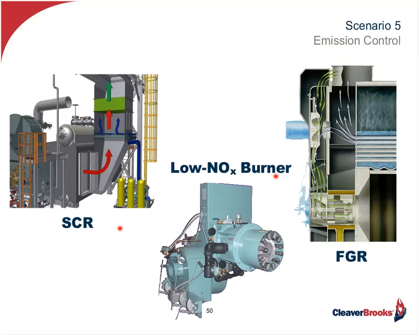So now what we use, we could be using ammonia as the reagent, either anhydrous or aqueous, or possibly urea would be the reagent that we would use to break this NOx down to something which would be relatively inert. So that would be selective catalytic reduction, with that ammonia then being applied to the catalyst, and it's across this catalyst that we get that reaction and reduce the NO and NO2 to inert gas.